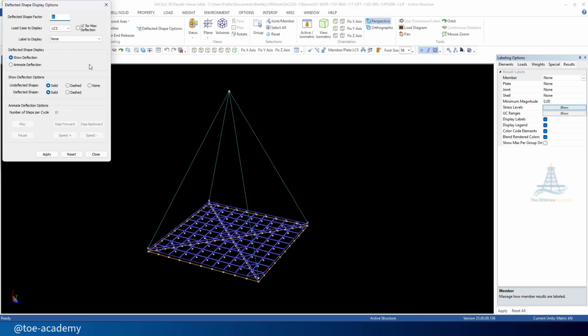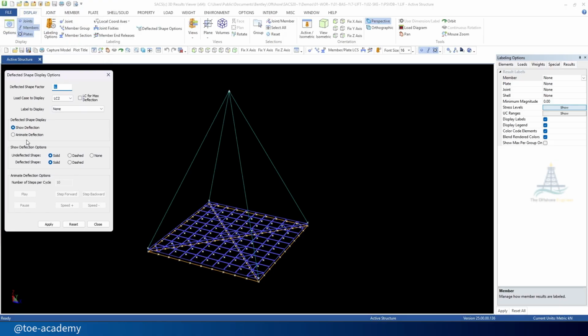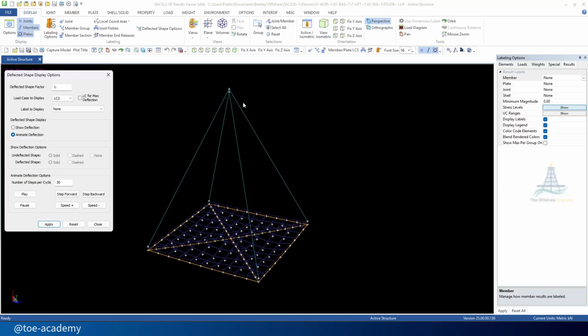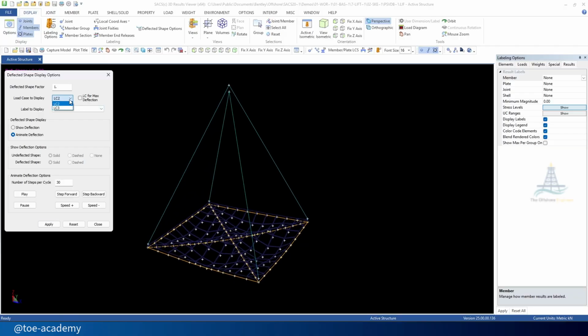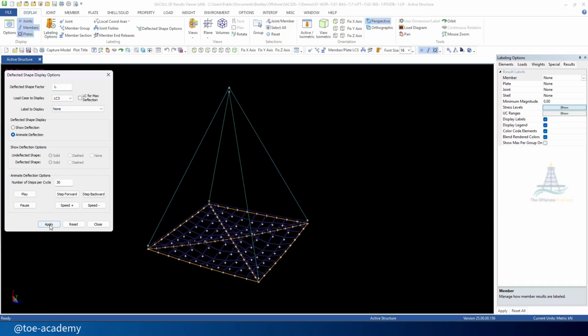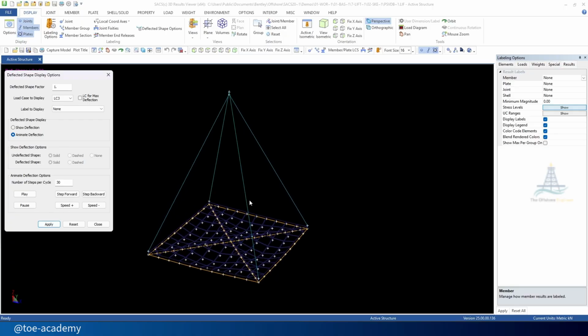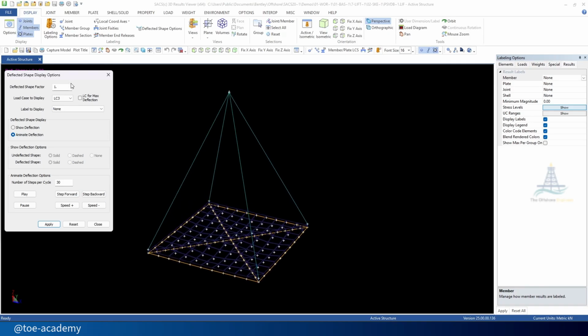So actual deflection behavior of a skew case is something like this. See, this is the actual deflection behavior of skew case. So this is with the 62.5% load acting upward. Now with that 37.5% load acting upward, this is the skew behavior. So the behavior is correct. If you have a bigger structure, you should have a saddle type of deflection behavior.